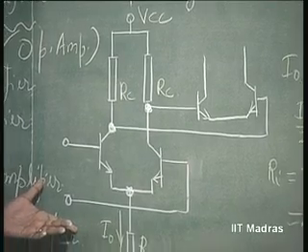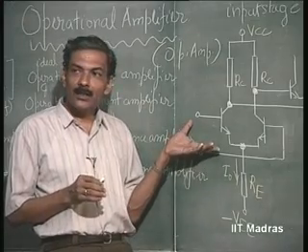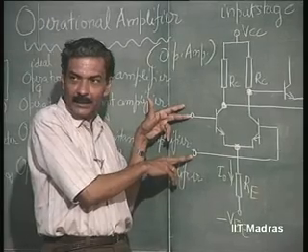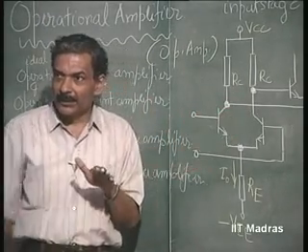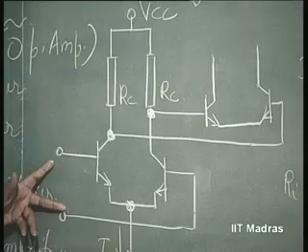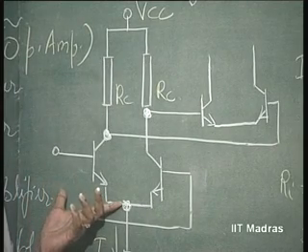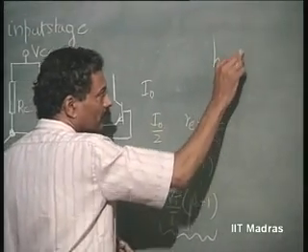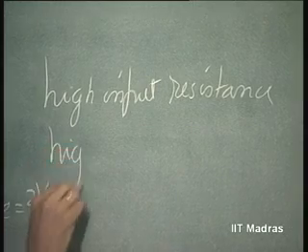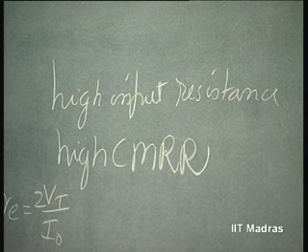First, input impedance should be high. It should get rid of unwanted people. That means these unwanted people may be the common mode signals. It should have high common mode rejection ratio. It should allow only the differential signal to be amplified, and you should ignore the common mode signal. This is trash. It has no business entering this building. So, it will select the differential signal from the composite signal. Now, that role is the major role. That means, apart from high input impedance, high CMRR is the responsibility of the input stage. Please remember this.